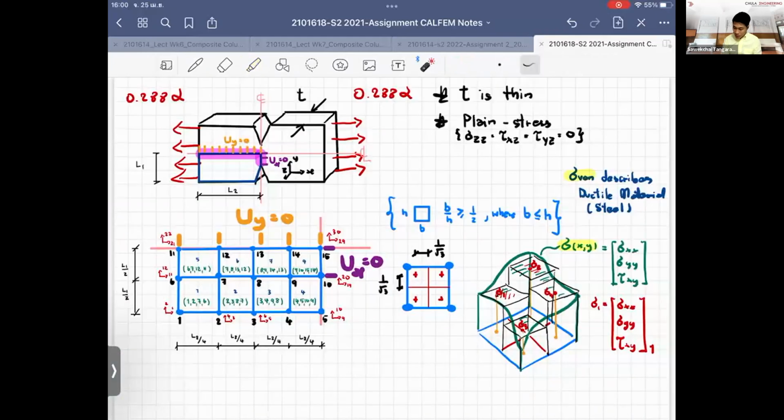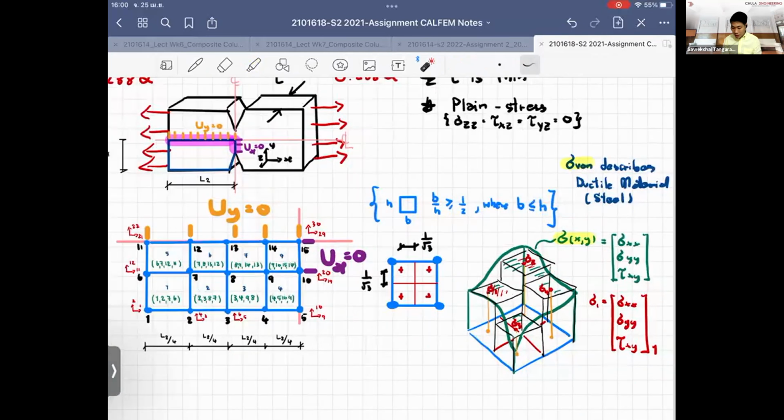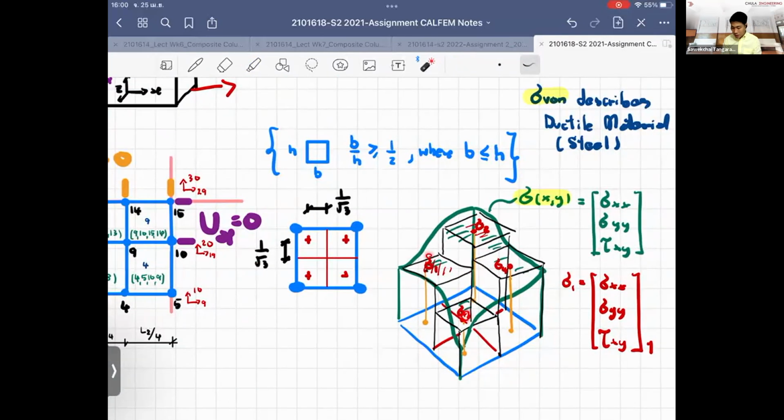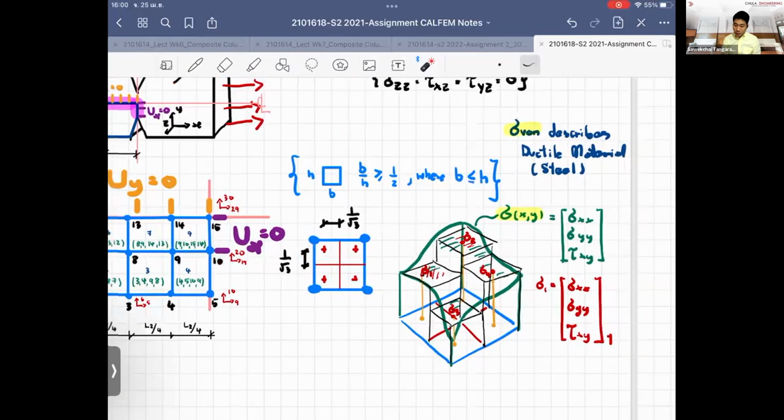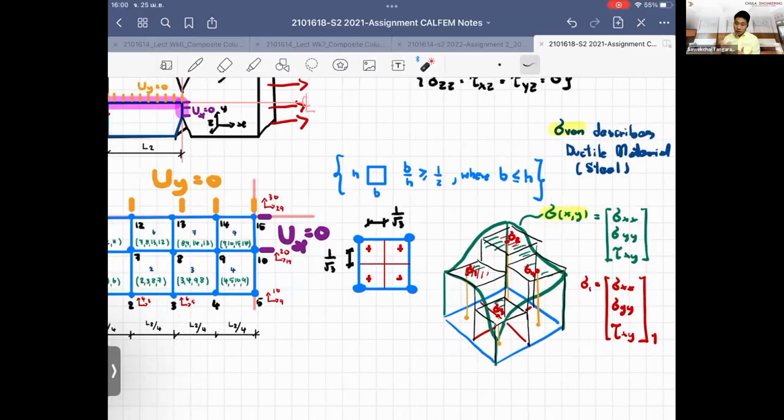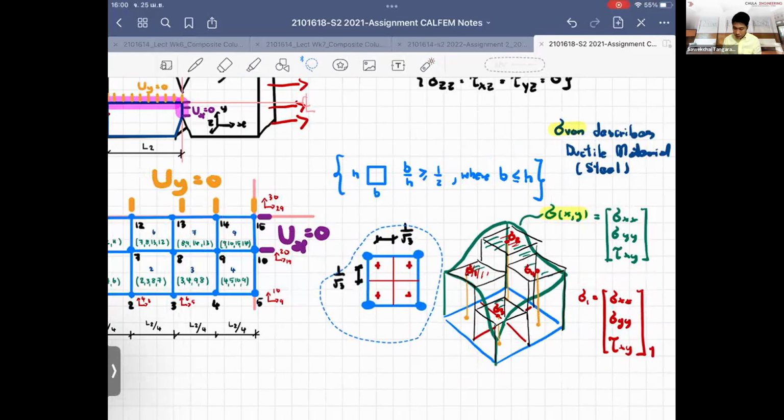You just take the resulting stress, the stress at the Gauss point, and that value of the stress at the Gauss point will represent the approximation at each quarter of the element, as I said, as a constant. So we approximate the hypersurface of stresses by using the piecewise constant field of the stress that we have at the Gauss point. Okay, and this is the meaning of it.